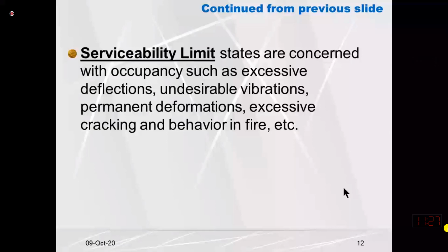I do not want the deflection in a beam to exceed a certain limit, say 20 or 25 millimeters. Even if the deflection is more than that, the structure is still safe, but I have put the limit. So these are the serviceability limits.